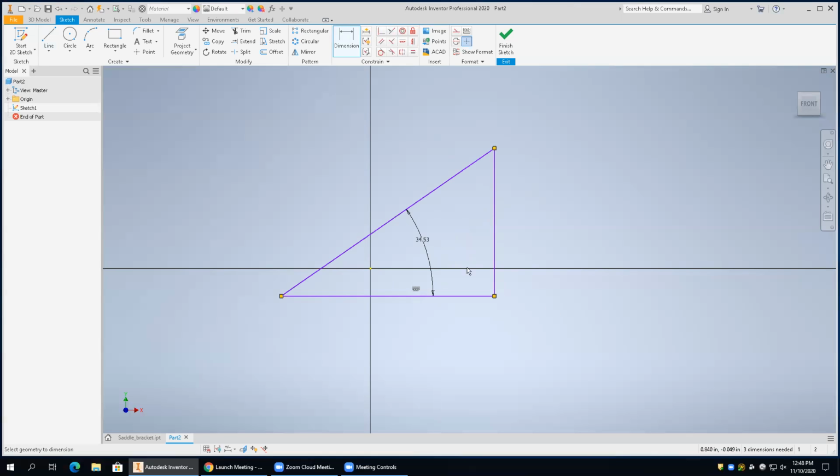So we're gonna double click on the angle. Let's make that, whatever the value is, just make it 45. And you should notice what it did is it allowed this to grow, but it grew vertically. But it kept that at 45, but it actually increased that. So those are constraints that are kind of cool. Let's show you another constraint that's kind of neat.